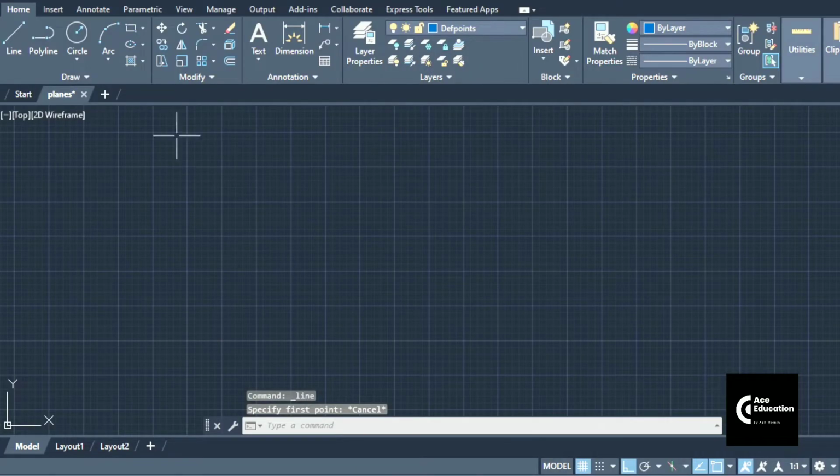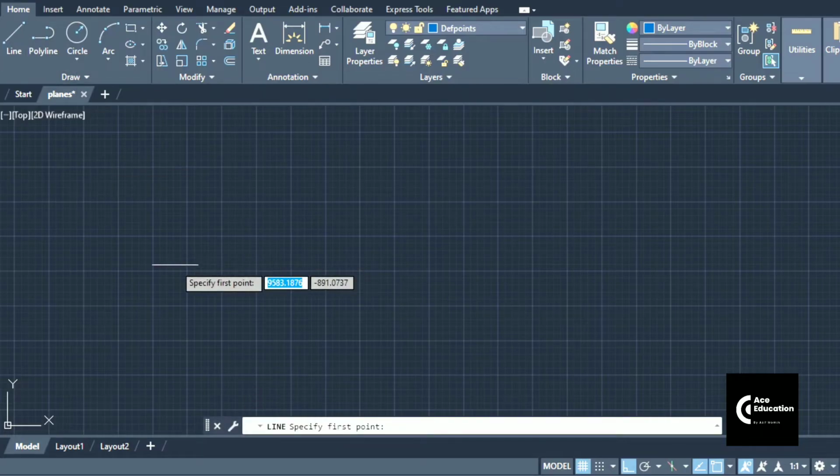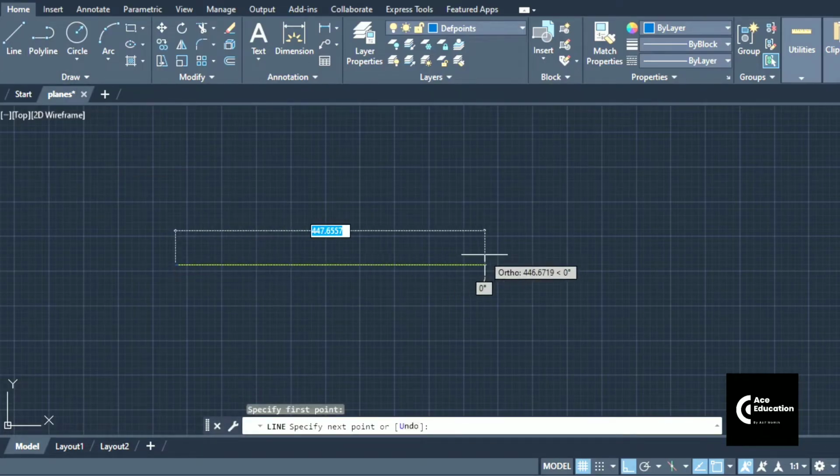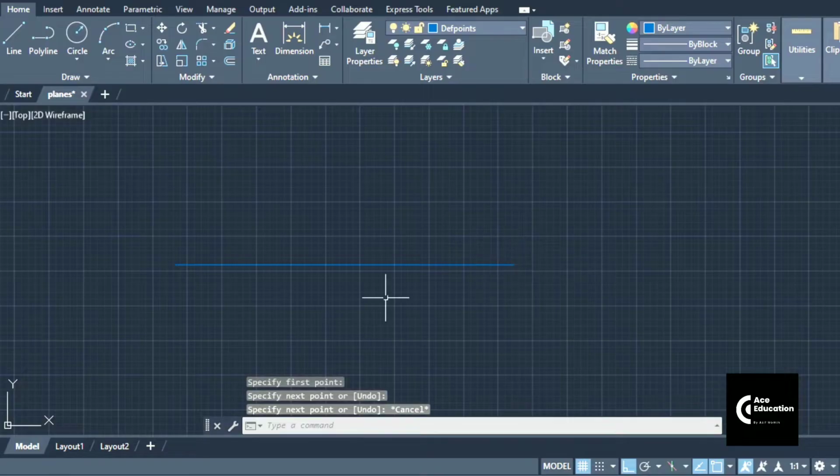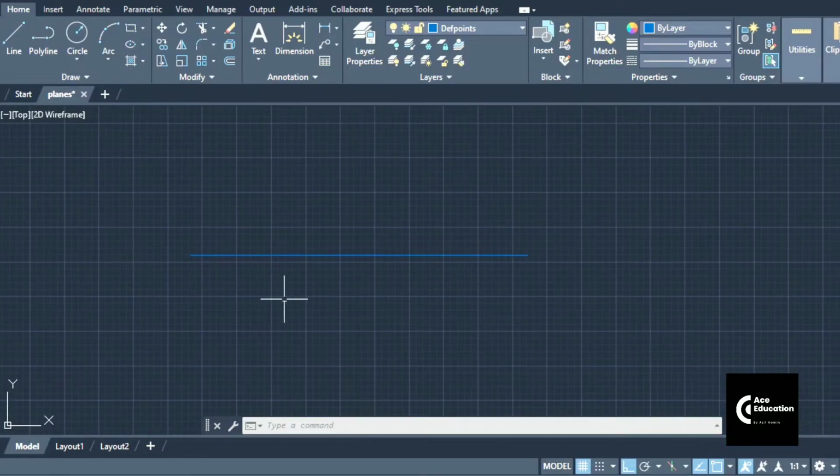Very first of all, we'll take the projection layer and using the line command, we'll draw the XY line. Now we'll be getting the true shape of the hexagon that can be seen in the top view. Everything that we are going to draw in the top view and front view can be drawn with the help of the projection layer only. So at the end, the removed part can be kept as projection only, and the retaining part we can darken with the help of the continuous layer.